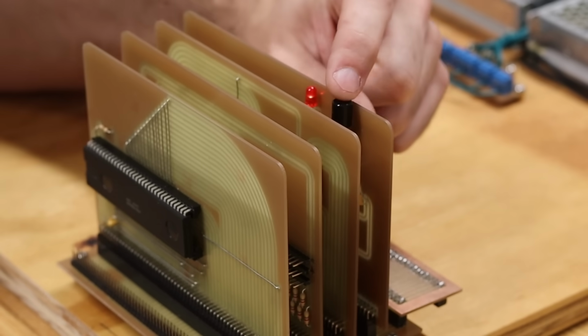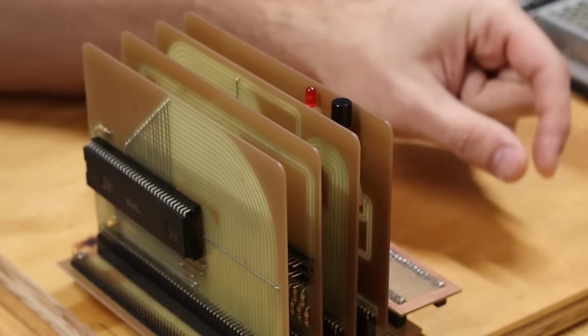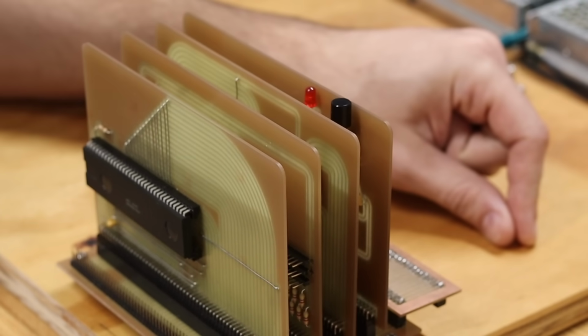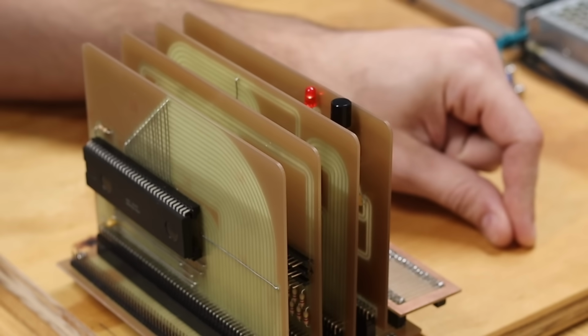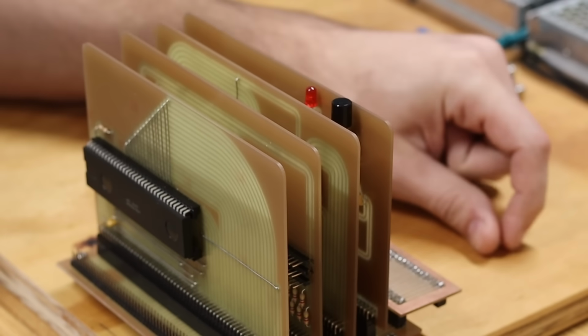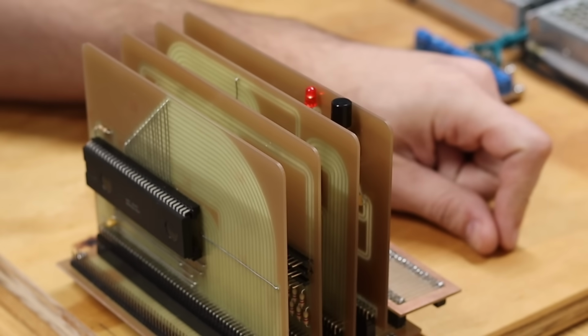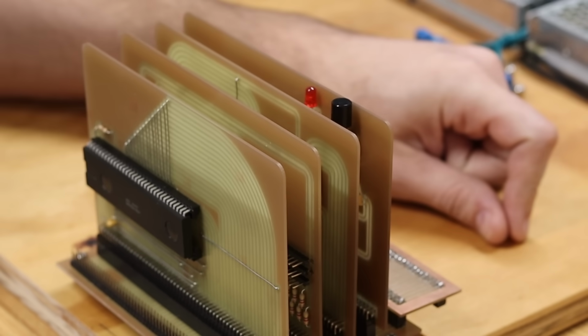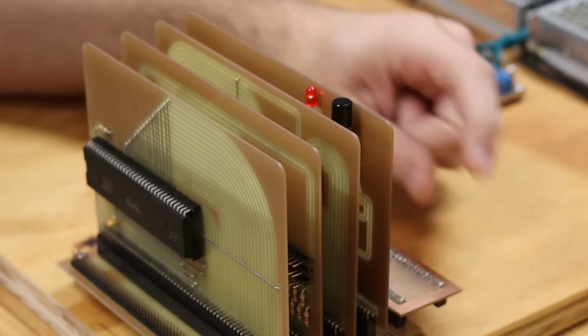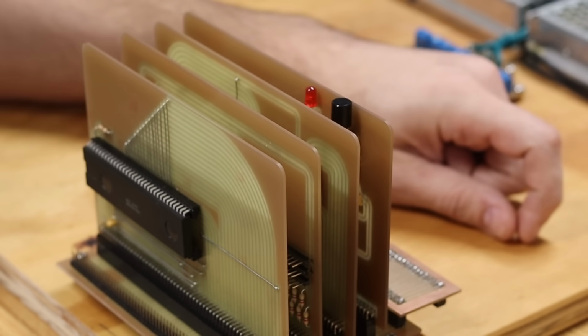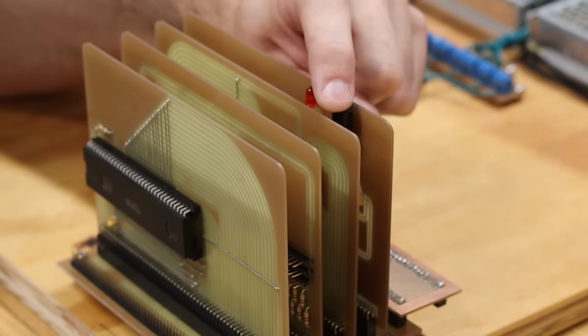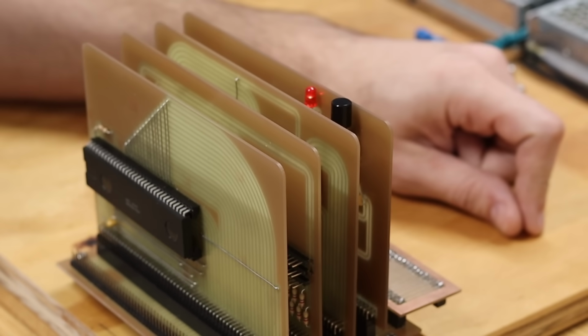The red LED came on. If I push the reset button, it reset. Oh, there it goes. That's an incredibly long reset. Maybe I need to rethink some stuff here. No, that seems a little more consistent now. I have no idea why it was so long the first time. My power on reset circuitry may need a little help, but for the moment it appears to actually be running.